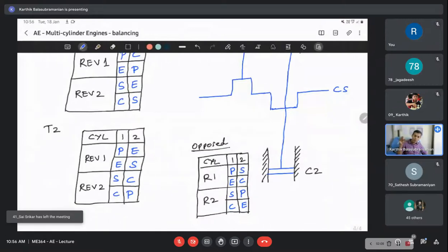So if it has to escape out through that hole, the back pressure holds the tire, and the loss of air from the tire is very, very slow because of the back pressure. It's extremely slow compared to a tube tire. In a tube tire, it can escape out through the gap between the valve and the rim. But here it cannot happen that way. That is why you still have some time before the tire becomes flat in a tubeless tire. And above that, you can have several other constructions like fluids and other things that some people are suggesting, which can further enable the tire to run for a longer distance before it becomes flat.